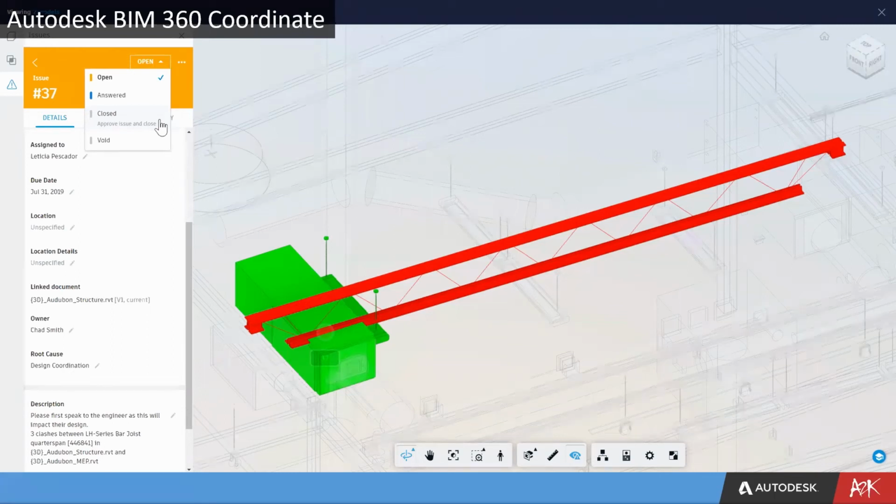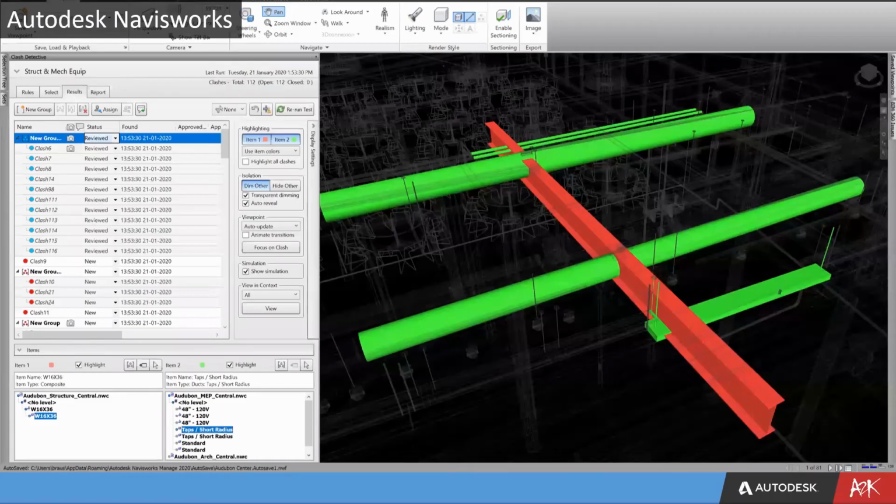So this is where we start tying it back into the BIM. It's not a large step for the machine learning to then assess the data for an automatic assignment of responsibility for this clash. And that idea of using machine learning or AI algorithms based on BIM data is becoming more prevalent. But of course, if you still want to do it the old school way, then products like Navisworks are still available.